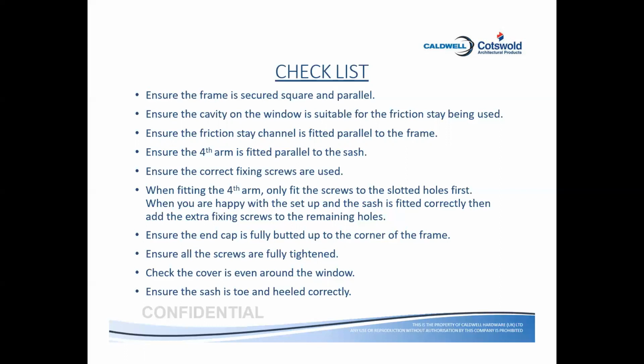Check the cover is even around the window. If the civil work is going on, you have to make sure the window is covered properly. On a couple of occasions everything is fine, the window is fabricated very well from the factory, but civil works keep on going and your arm gets accumulated with dust, with cement, with plaster of Paris, and people try to open the window.